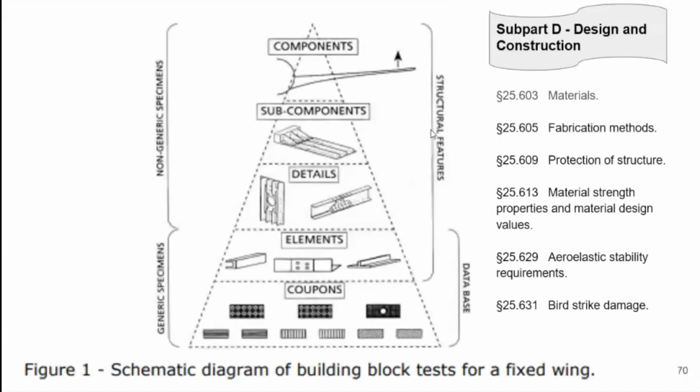In summary, again, for the certification of composite, we shall begin from the bottom here, where you need to develop the properties for us to do the design. You need to determine the stress and the strength: FTU, FTY, FCY, FSU, modulus of elasticity, FBRU bearing, FBRY. Those are here, and those values are used during our stress analysis.